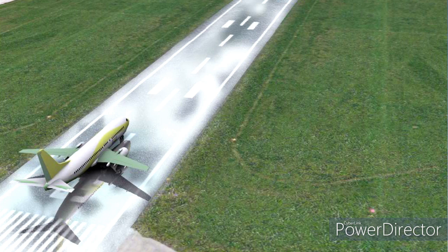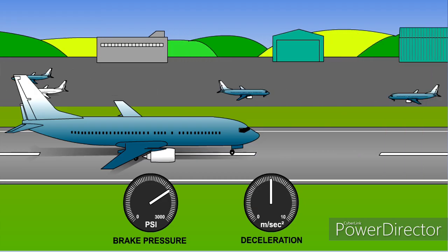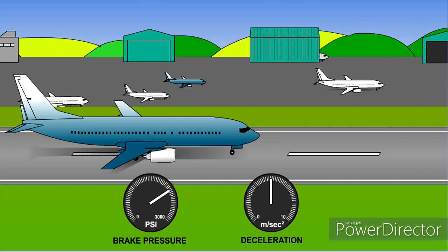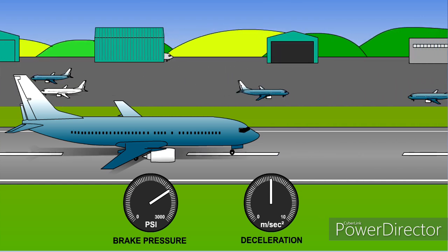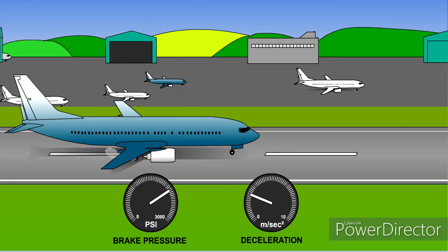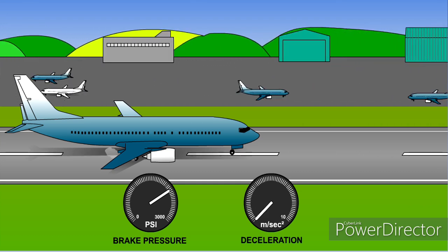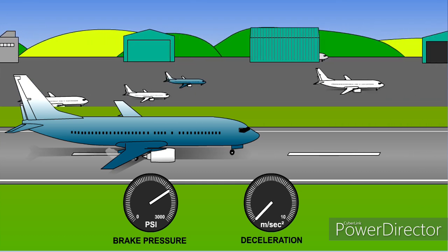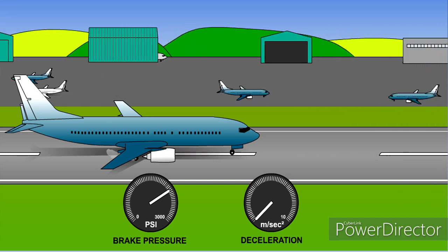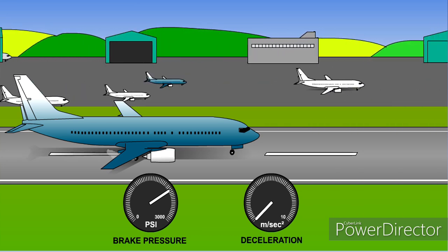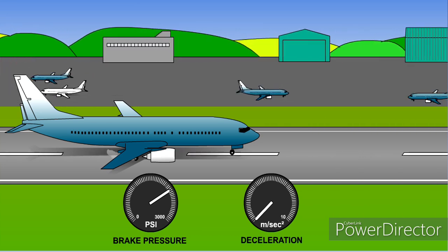The pilot is unable to sense when the wheels lock, and so the primary requirement of a brake modulating system is to provide skid prevention. Whenever braking torque is developed, there must only be a small degree of slip between the wheel and the ground. A skidding wheel provides very little braking effect. In all brake modulating systems, the deceleration of the individual wheels is taken as the controlling parameter of braking torque.